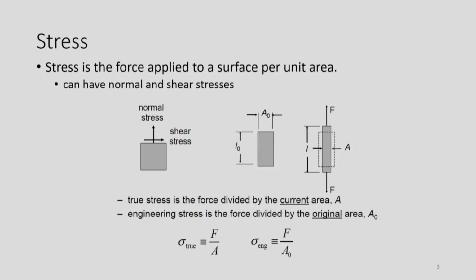That means when you are compressing or pulling, for example, you take a plastic sheet and pull, it slowly expands, but the cross-sectional area is also changing. It becomes thinner in the middle. That's what we calculate in true stress; we account for the change in cross-sectional area. But engineering stress uses the original area that you are measuring, and that's it. You will not change the cross-sectional area for calculations.